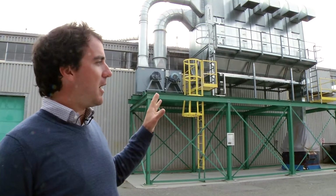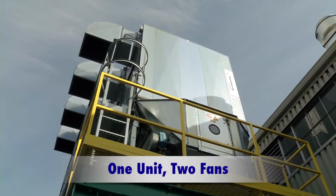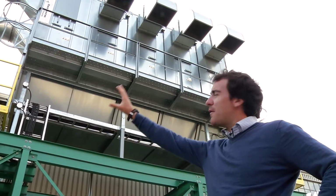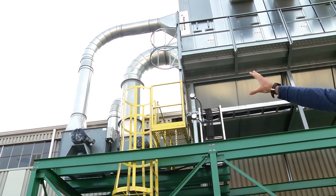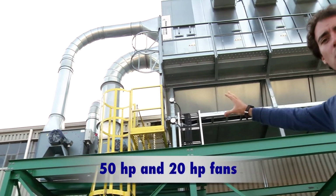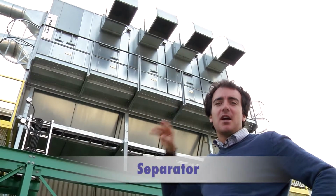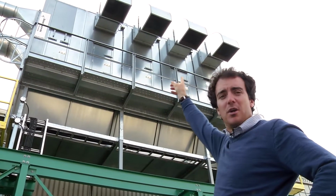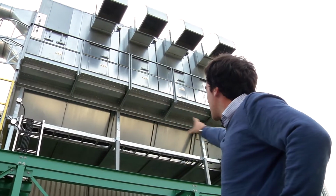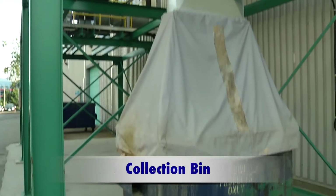The conversion is that we went from these 6 units to only 1 unit that you see behind me and only 2 fans. So the process in a nutshell, you have the fans extracting both air, dust and shades from the building. All of those elements will go through the fans into the separator where the dust and the shades will fall into a conveyor. The air will be exhausted through the outlet and the conveyor will bring the dust and the shades into the collection bin that you see at the bottom.